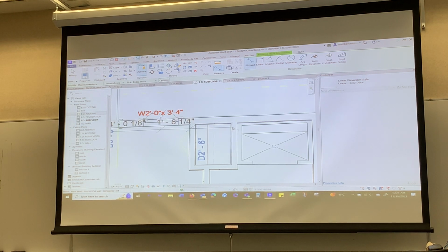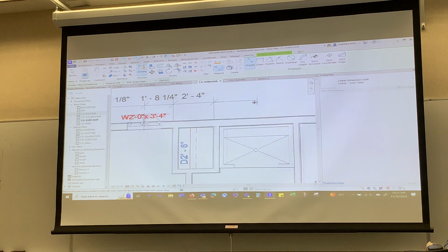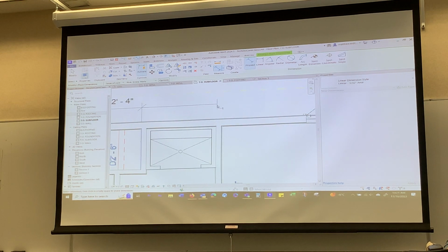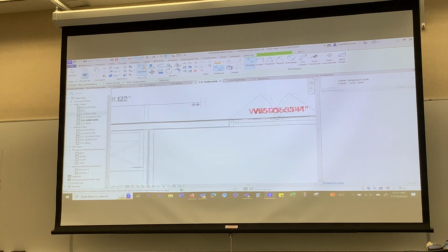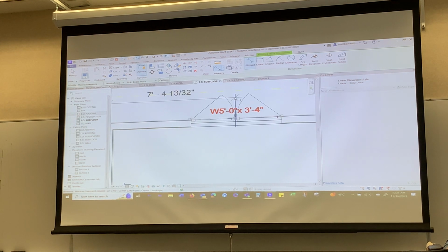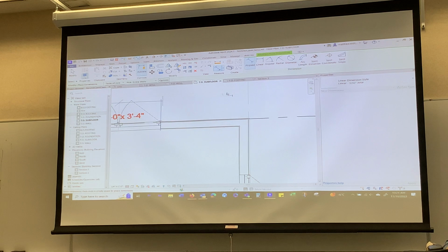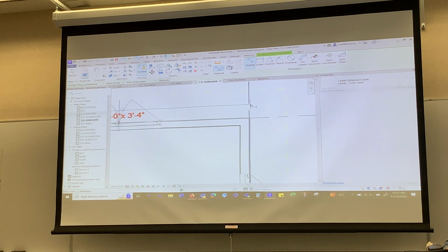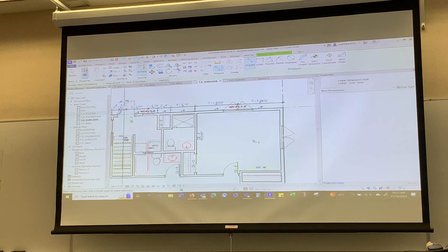Framers like this. I know, because I framed a lot of houses and it's way easier on your brain. This is a tough one. I can't necessarily find it. That's the edge of the shower. That's probably correct, but I could come to there just to verify. Yeah. Center of the window. And then I'm going to use the grid line because I know that's the outside of sheathing. Then I'm going to come out here and, don't select that, that's the roof. I'm going to select nothing, and that ends the string. How slick is that?